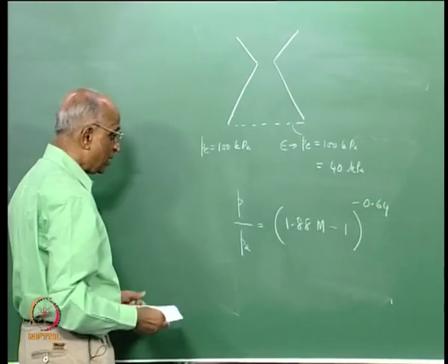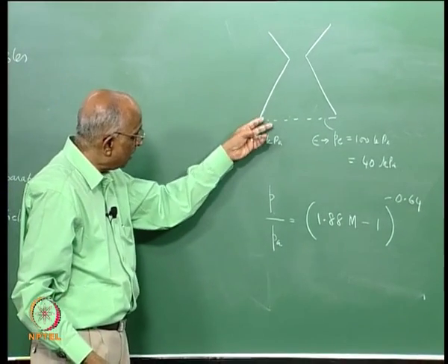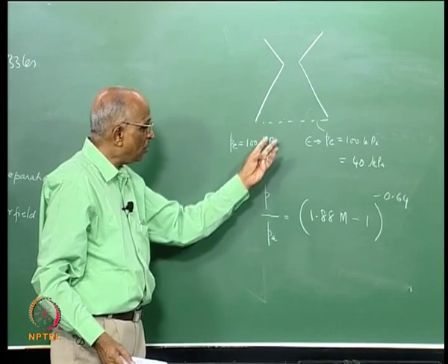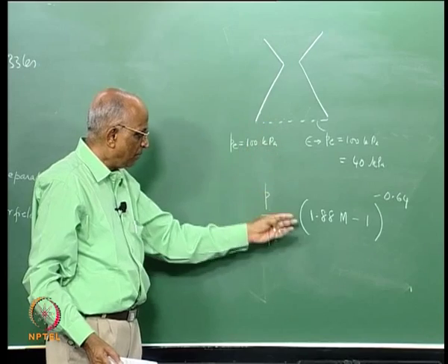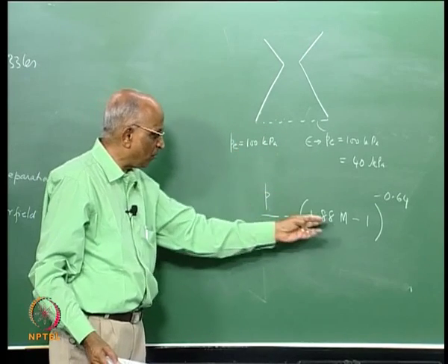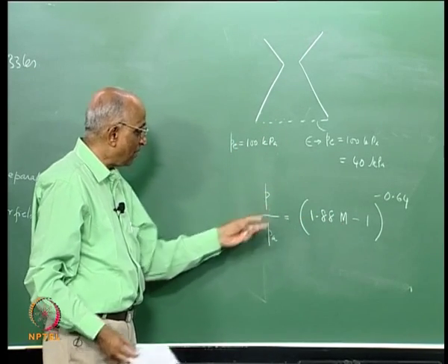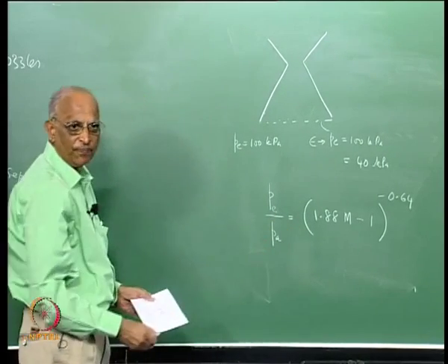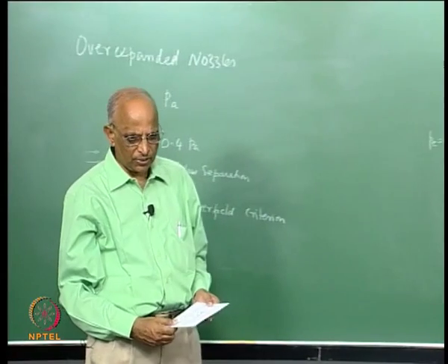Based on experiments, it is not only the inertial force which delays separation to a constant value of 0.4 times the ambient pressure, but it depends on the local Mach number at which flow separation takes place, and this is the value of the exit pressure for which flow separation takes place. This is again based on experiments.